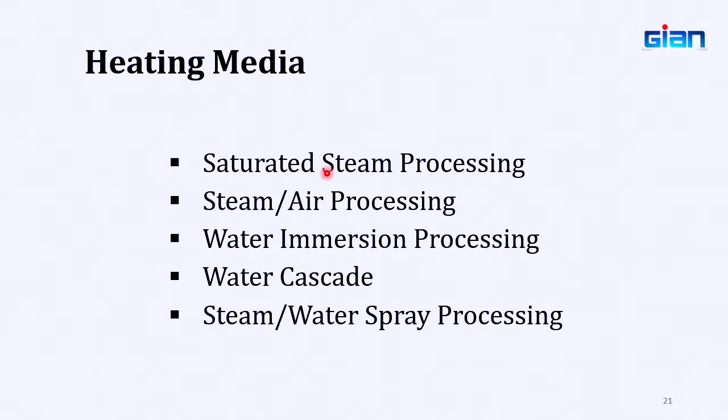So when you're doing cooling, actually you collapse the steam, but air would still be there. That air would exert some outside pressure. Still there is a pressure differential, but now it is much lower than if it was only pure steam. So with that, the seal is able to maintain its integrity. So that's why steam-air processing came into play.